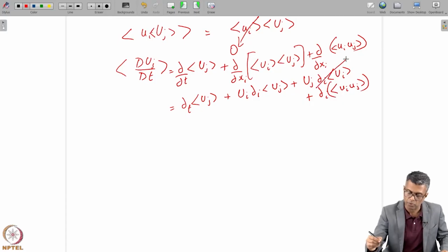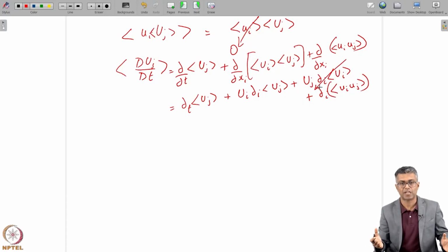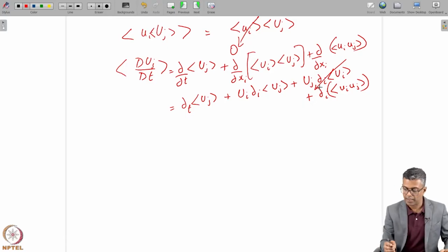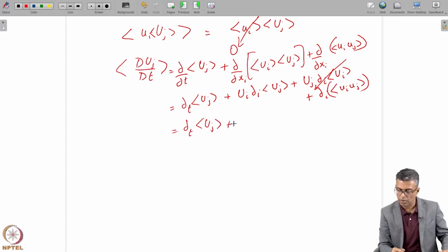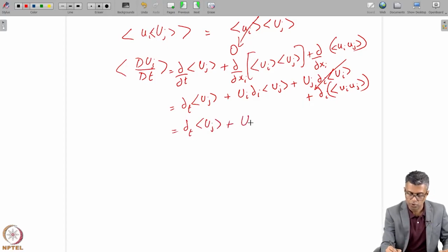Now this term goes to 0 because the mean velocity satisfies continuity. Then what you end up having is del t Uj plus Ui del i Uj. I'm sorry, this is mean, right? This is mean.